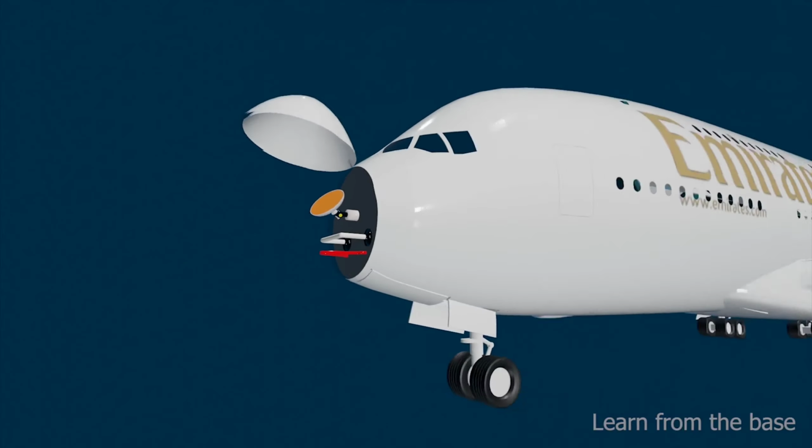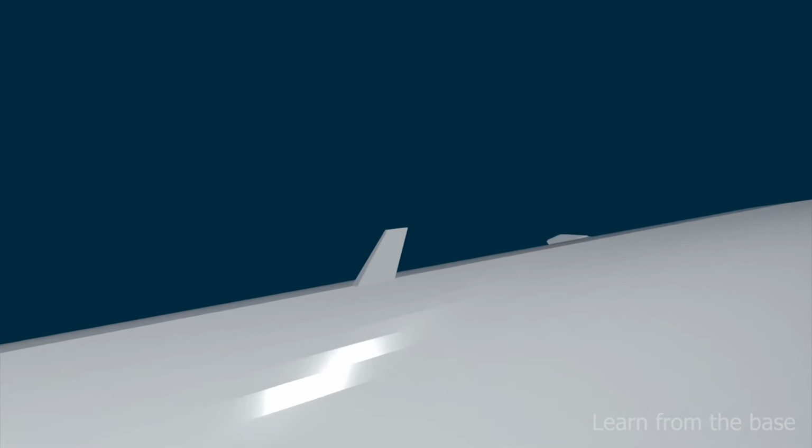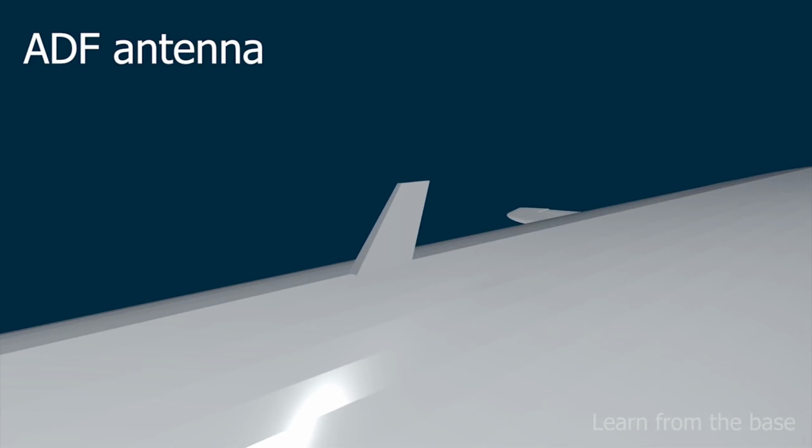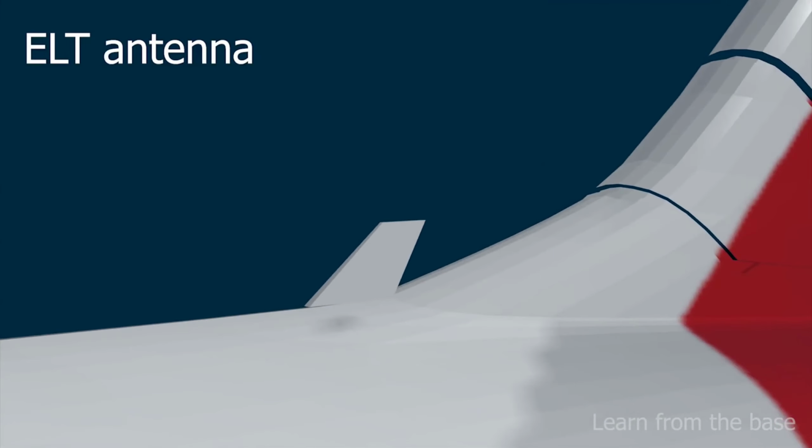The VHF antenna. It is a communication antenna. It is capable of transmitting and receiving signals in the VHF band from 118 to 156 MHz. The ADF antenna. ADF stands for Automatic Direction Finder. It is an aircraft navigation product that automatically calculates the relative bearing of the aircraft to the radio station. ELT antenna. ELT stands for Emergency Locator Transmitter. In the event of an aircraft accident, these devices are designed to transmit a distress signal on 121.5 and 243 MHz frequencies.